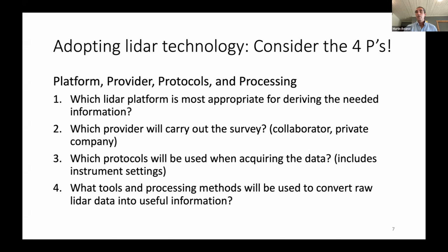The protocols that are going to be used to acquire the data: sometimes you need to set the instrument in specific places if it's terrestrial, or determine the height of your flight if it's airborne. The instrument also has some different settings you can use. And lastly, and very importantly, which tools you're going to use to process your data.